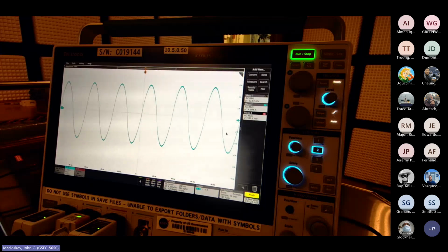This tells us that our source impedance is looking very close to half an ohm at 30 hertz. That's good. That's what we expect. And this means that if you do this pre-cal without monitoring the current in real time going into the EUT, your short circuit current limit at 30 hertz will be 4 amps.